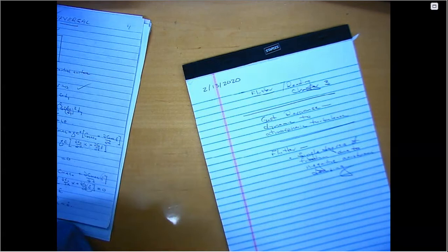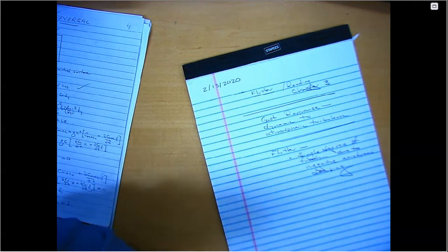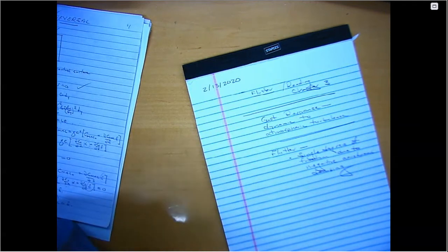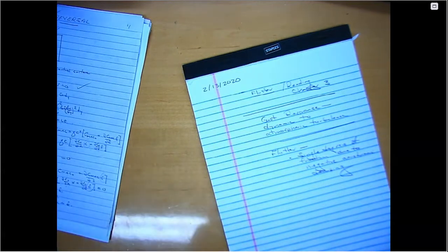So now you have to find the phase angle that is most likely to lead to the most critical flutter condition. Right? In turbomachinery, you have that. In the case of airframes, typically you might have a few dozen modes in a flutter analysis done by an aircraft company, and you have to look at all of them to see which one might exhibit flutter.